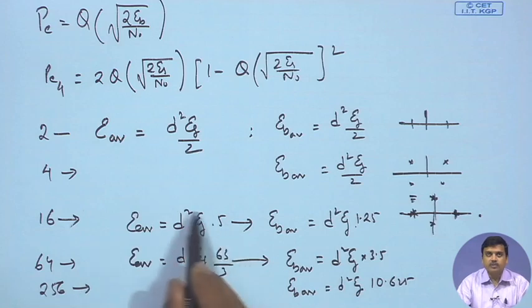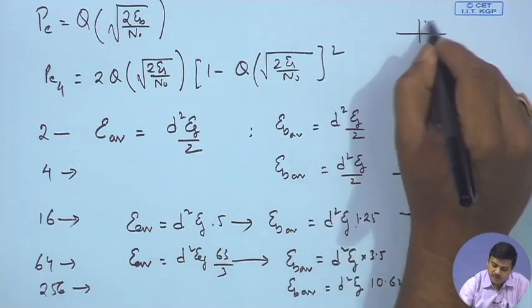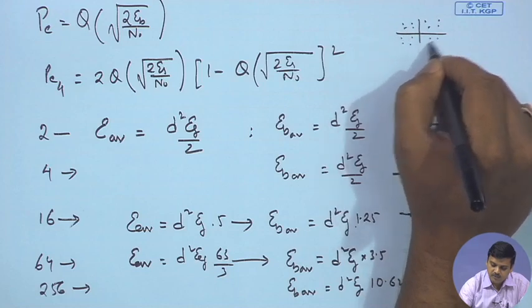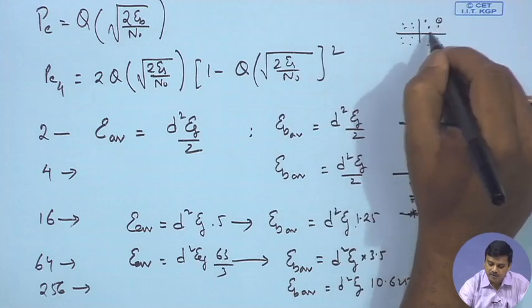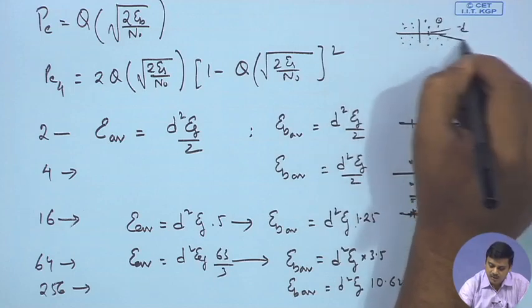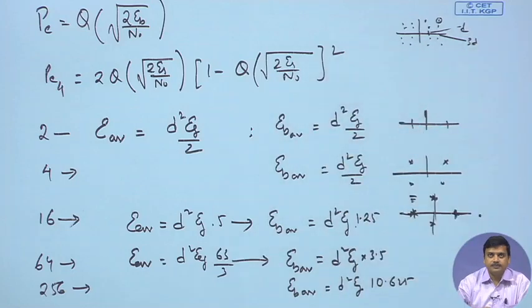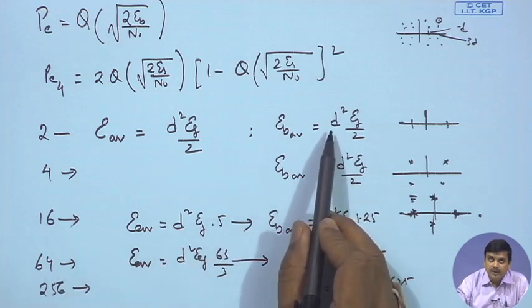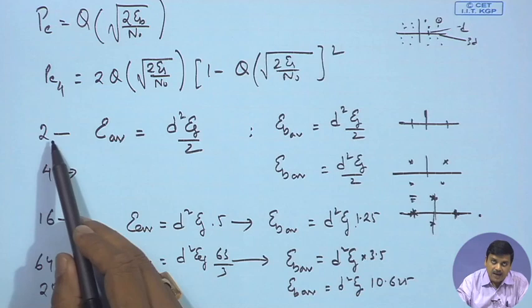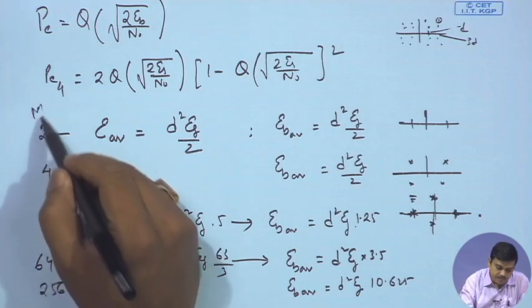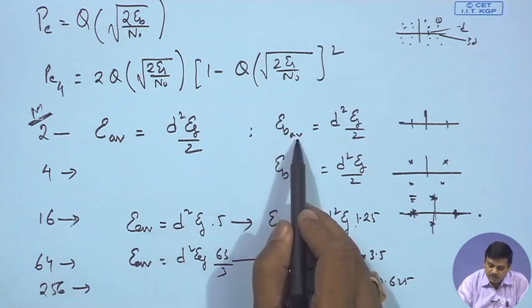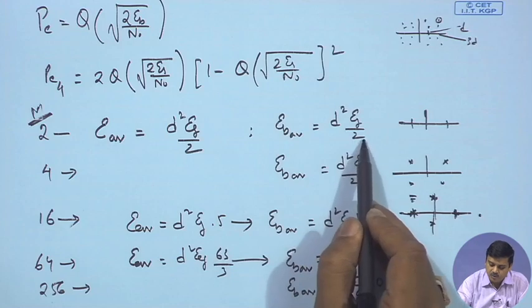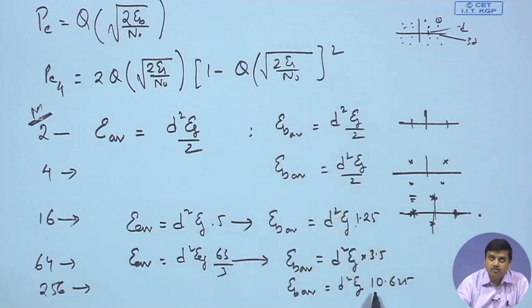So, these calculations will be based on the method that we did. That means, if you have constellation points all over, you have to calculate the energy of this, energy of this, and energy of this, and take the average of it. And this could be d, this could be 3d, and so on, following the same methods. So, if we have to keep the same minimum distance, that means if we keep d constant, what we find is as we increase the M, that means the size of the constellation, the Eb, energy per bit, is related to the pulse energy and d in the form over here.